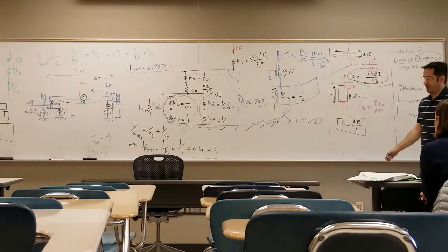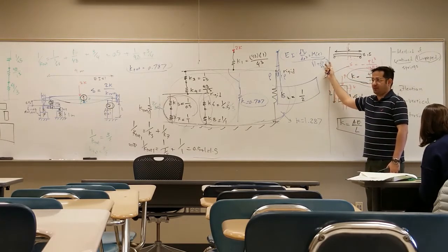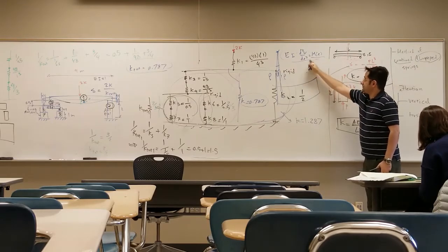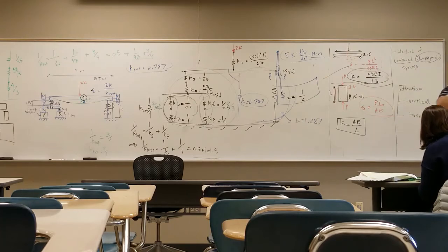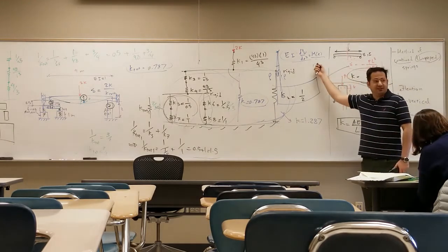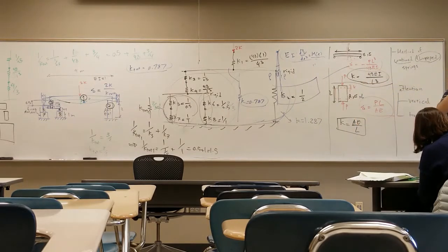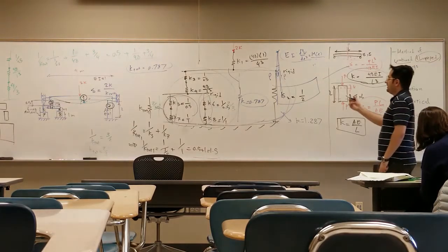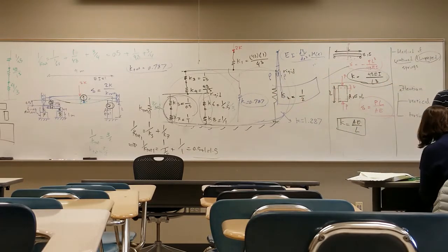And since dv/dx is small, this value is small, so this almost becomes unity. But in order to get the error, you have to go back and model that term that you dropped. How much is that bound? That depends on the type of the beam, the cross-sectional area, and the location on the beam. So it's not a simple formula, it's a complicated formula.